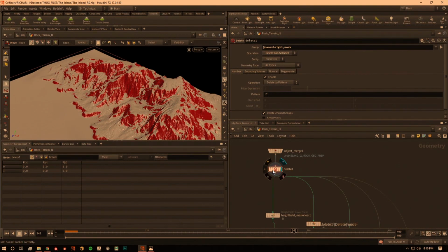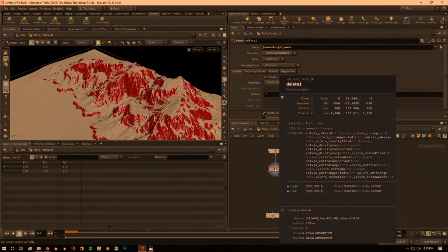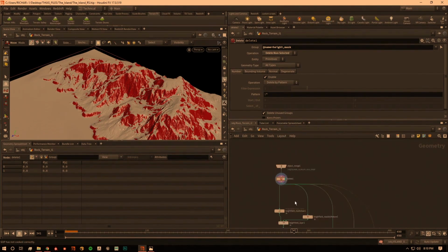But one thing I learned while working with Houdini is to keep an open mind, because anything can happen here. One of the developers told me that this SOP node works to delete volumes as well. So you just have to specify the name of the layer, and it will get rid of that.